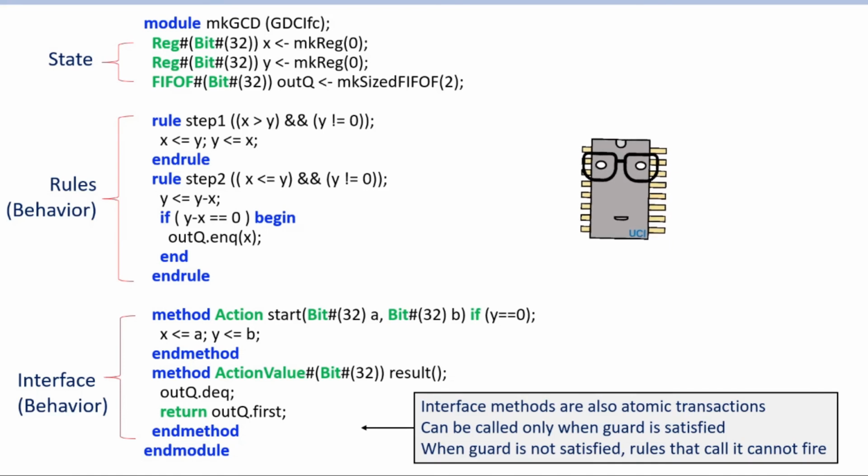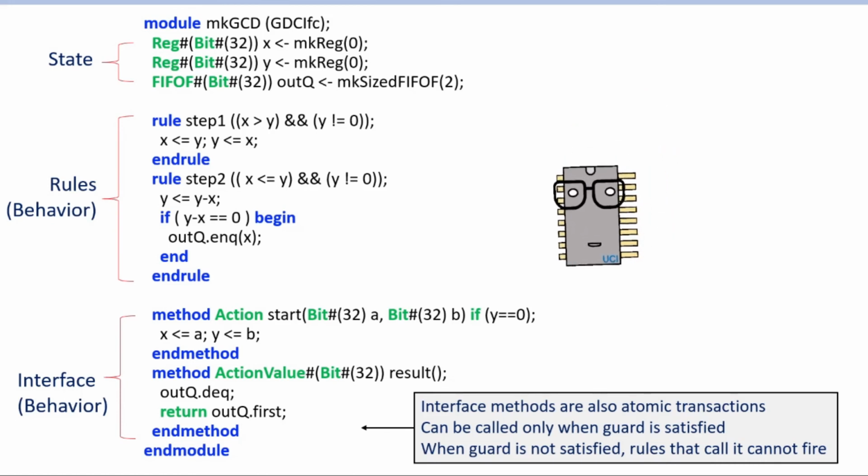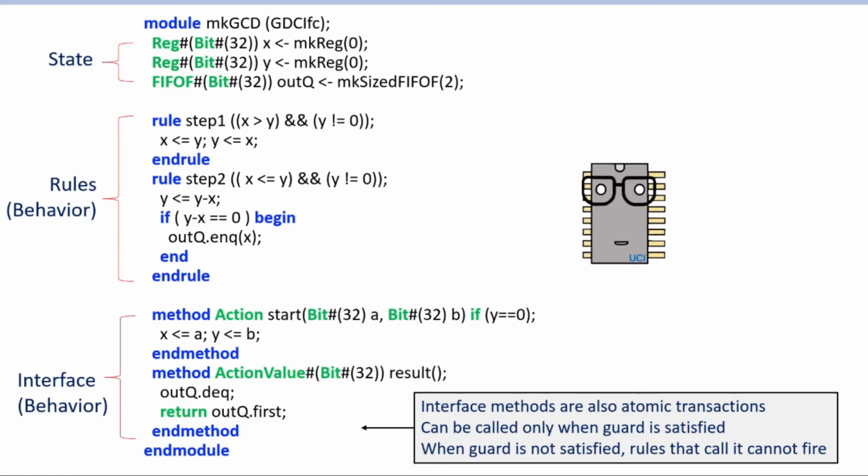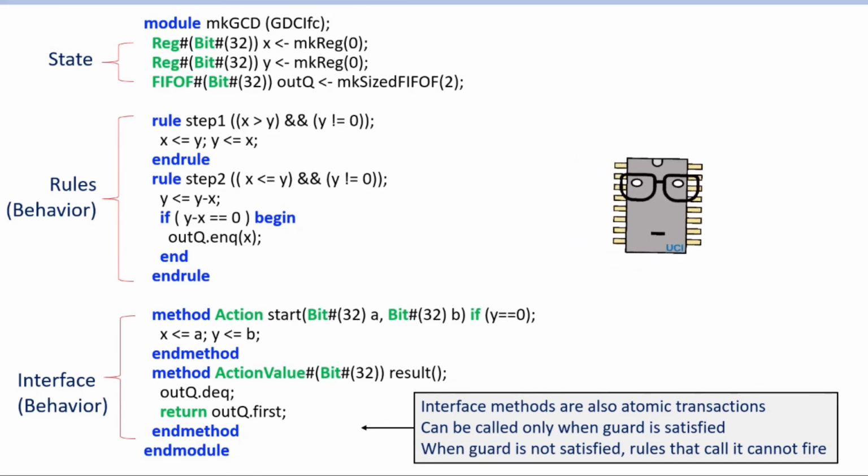But a potential benefit of doing it here in the FPGA could be that the design of mkGCD is so simple. If you had an application which is heavily reliant in terms of performance on calculating GCD, you could potentially stamp out hundreds of these things, as many as would fit on the chip, on an FPGA and parallelize the work if your application supports it. And that's one way you can actually get high performance out of this.